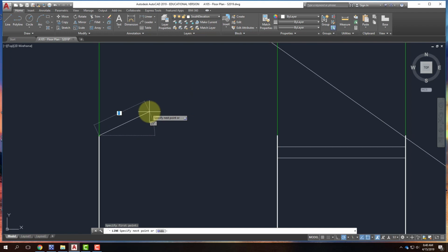And so you've probably heard in the past, roofs are designated by like a 6 and 12 or an 8 and 12. And what that means is for every 12 inches of run, you're going up by whatever the smaller number is. So if it's an 8 and 12, for every 12 inches of run, you're going up 8 inches. Right? Or for every 12 inches of run, you're going down 8 inches. It's the same. It doesn't matter which direction. So typical roof around here is somewhere between a 4 and 12 and a 6 and 12 if you have a pitched roof. That's normal for around here.